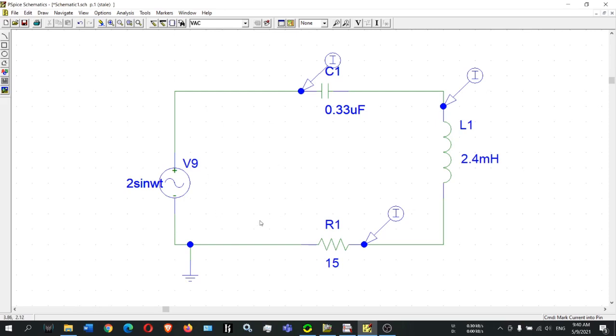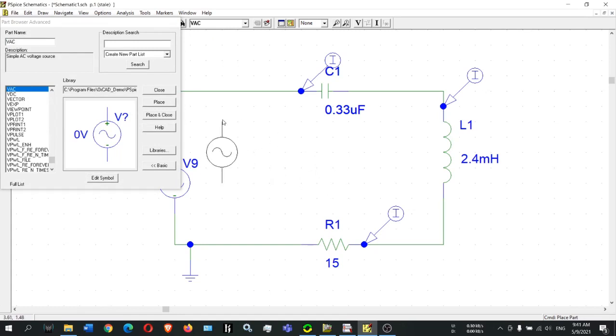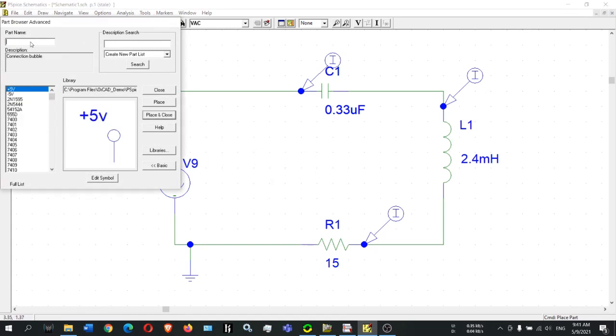I'm going to present about part B, series resonance circuit, and how to simulate this circuit. Okay, firstly we need to construct this circuit by getting all the components right. So firstly we click the get new part, and then for the voltage supply we use VAC, we could place it anywhere, VAC component. And then for the capacitor we just write C, we get the capacitor part, and for the inductor we write L, we get inductor, and resistor we write R.